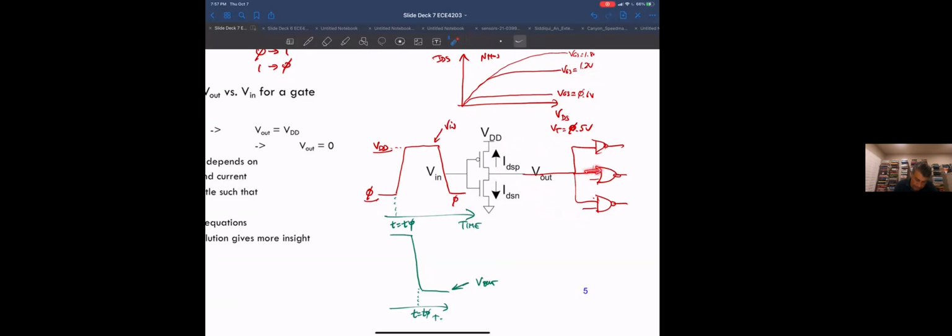We saw that in a MOS transistor, when you go from the transistor being off to when it has a channel, the capacitance increases significantly. So it's a nonlinear capacitance that these two transistors are driving. This guy's pumping current into this nonlinear capacitor, and this guy's pumping current out of it, not at the same time.